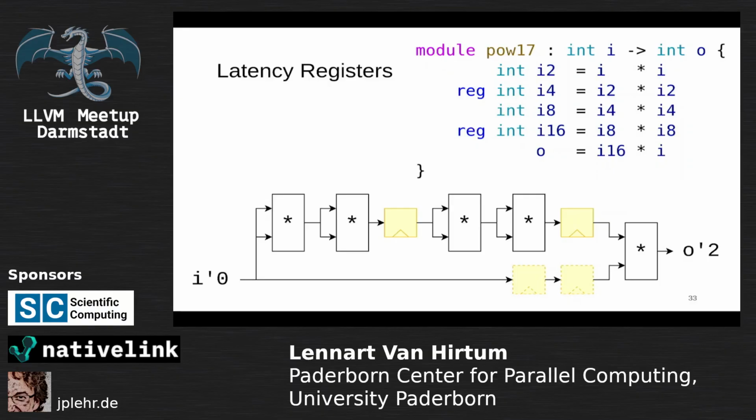And so if we follow this along, that will mean the compiler figures out that O should have an absolute latency of 2 here. And from these absolute latencies, the compiler then inserts the necessary pipelining registers to balance out these latencies. So here, because of the gap, it will find, okay, I need to put a register here, I will put one here. And also because this has created a gap between these 2 wires, the compiler has to insert 2 latency registers there to keep everything in sync.